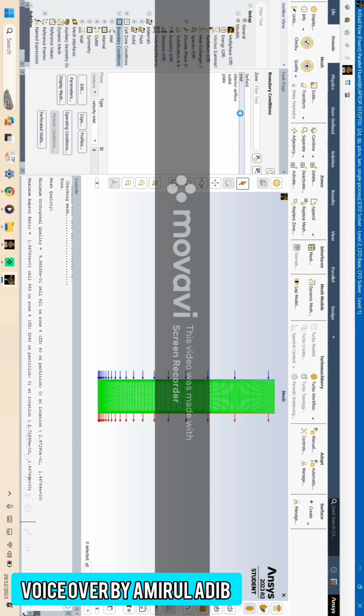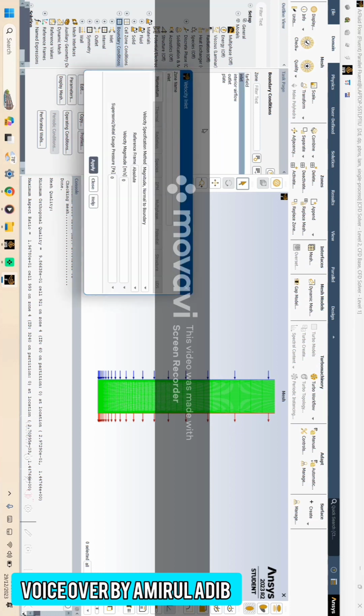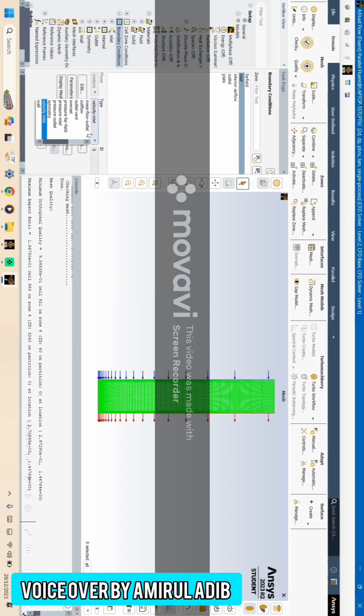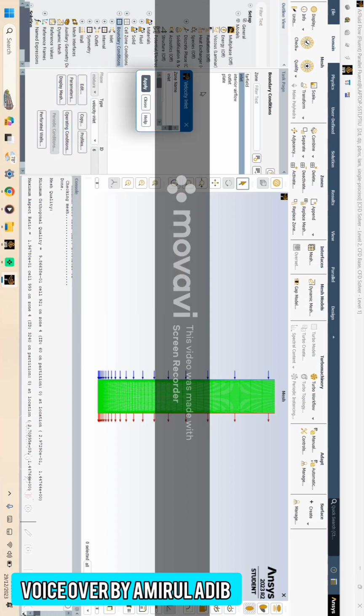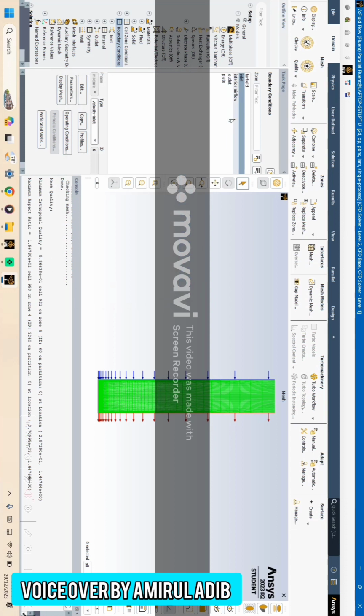and for the inlet we double click and change the velocity magnitude to 1.5 according to our data. Our data has two velocities, 2.5 and 1.5. We choose 2.5 first, and then close. This is interior airflow. For the outlet, we choose pressure outlet. The plate is wall.